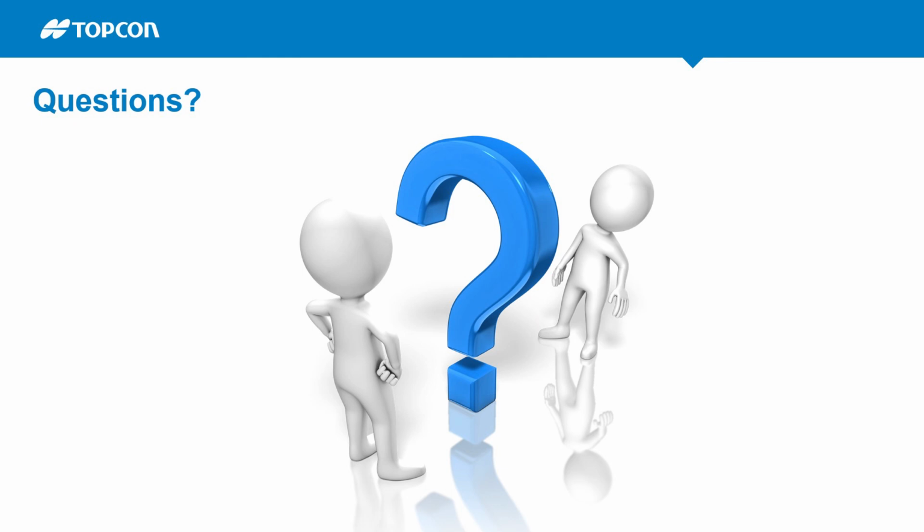Short answer is no. As long as it is a non-unified ReCap project, you can use that data with Verity. That being said, I would highly recommend the GTL. The reason for that is since the GTL is built upon a robotic total station, you can get probably the most accurate point clouds on control. And having a proper alignment of that point cloud in the known coordinate system is basically critical for getting the most accurate result using Verity. Did that answer that question?